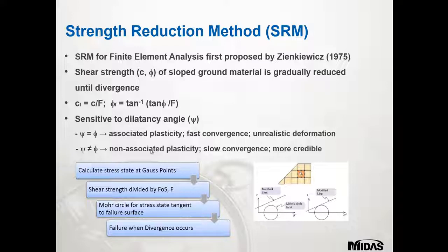So the strength reduction method can model situations including effects of different types of reinforcement, surcharge loads, and groundwater conditions. As it was said in the previous webinar, input of elasticity modulus will also affect how the deformations will occur within the soil, and if reinforcements are present, then their relative ratio would determine the development of strains and displacements as the material shears. So just to go back into the software and show you the